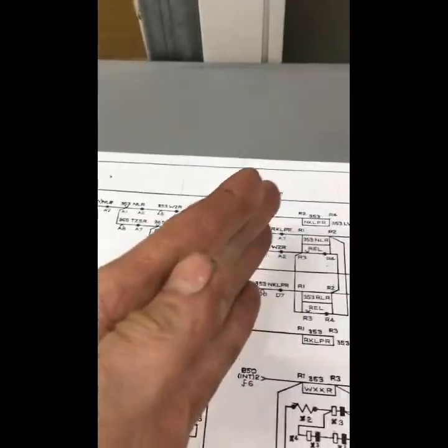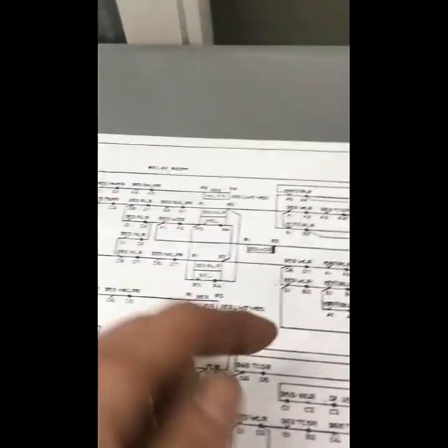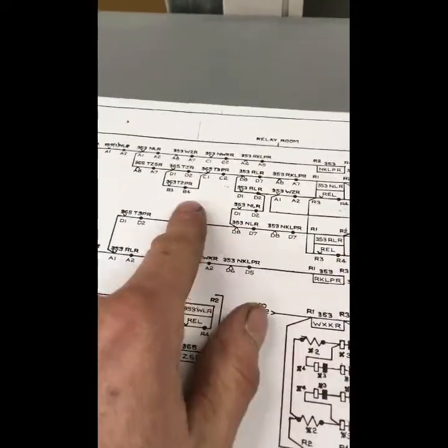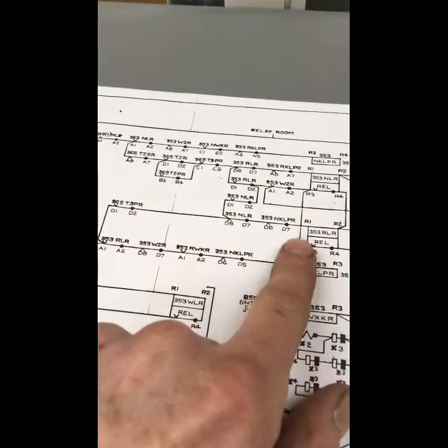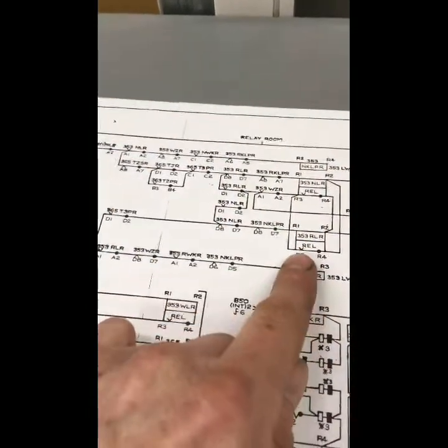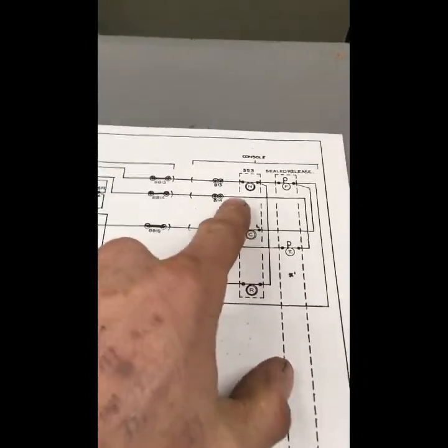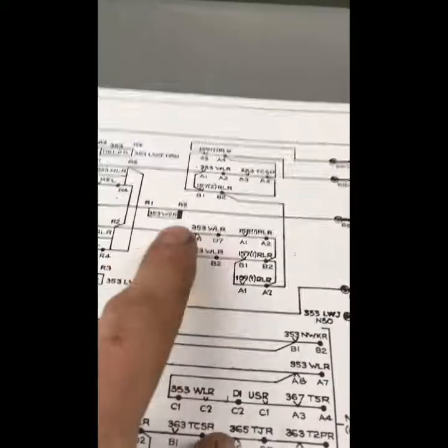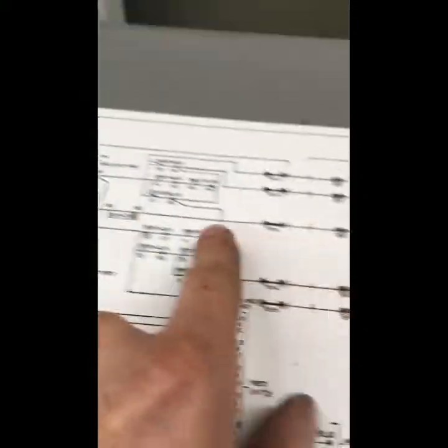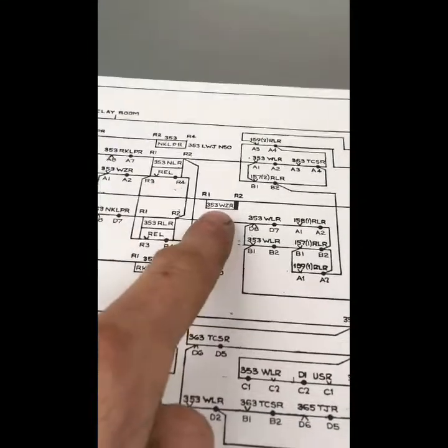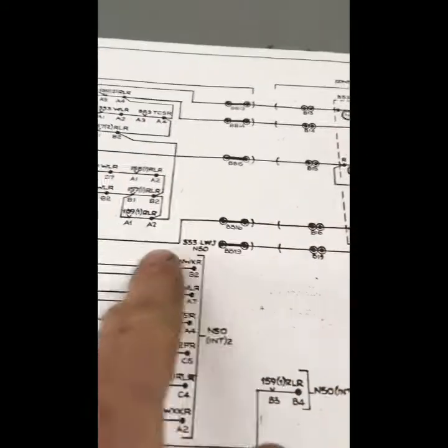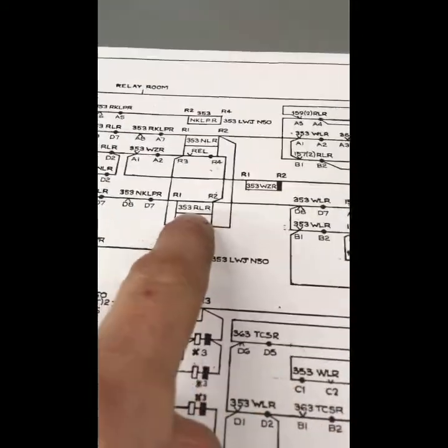Everything to the left is the interlocking. This is all the interlocking running itself. If permission is allowed to be able to move these points, all these circuits will align to allow the feed down. If not, they will not allow him to do it. So even though he can request reverse and normal, nothing will happen if the interlocking does not agree. So as long as the points are in the centre position, the interlocking runs the show, calls the WZR, calls the points. If, however, the signalman decides I'm going to put these reverse, he will drive the RLR.